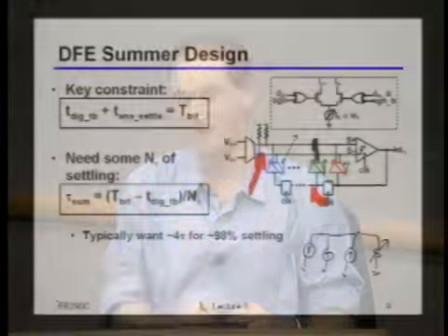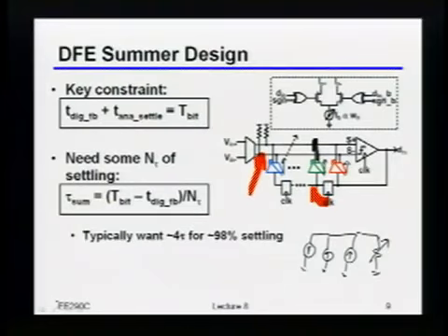But I'm still talking about, let's say that I try and build this thing, and I look at all of my channels, and I figure out that over all of my channels, just the worst case on each one of them, when I add those all together, is just too large. It's just too much capacitance for me to close the loop at that speed. What can I do? Like the shuffling stuff? Similar. Cascode? Okay, that also turns out to work, but for a different reason.